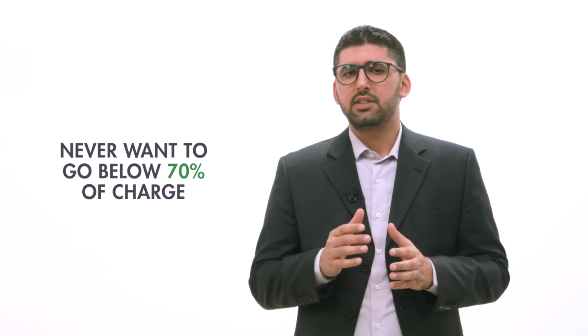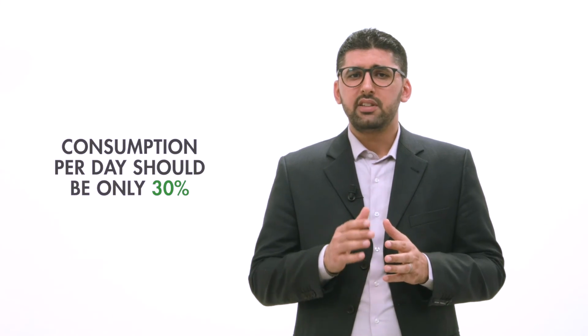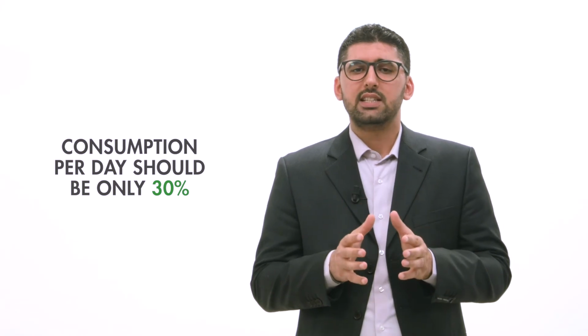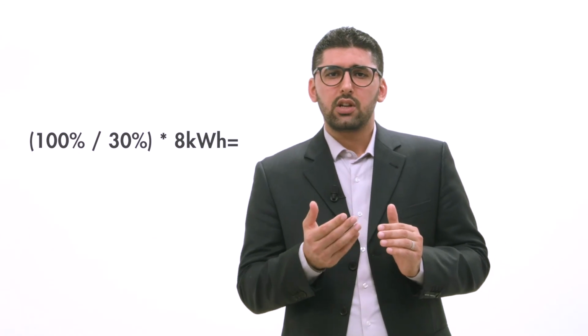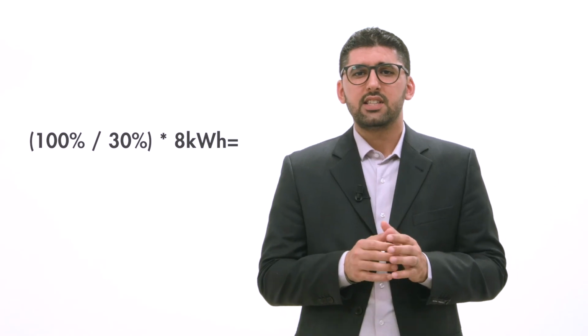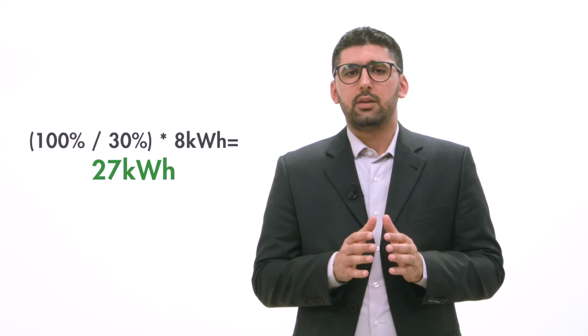As for the batteries, we never want to go below 70% of charge, and this is to save the lifetime of the batteries. So our consumption per day should only be 30% of what's stored in the batteries. Therefore, the size of the battery system should be 100% divided by 30% times the total consumption of the load per day, which is 8 kilowatt hour. That gives us 27 kilowatt hour, and that is the size of the battery system.